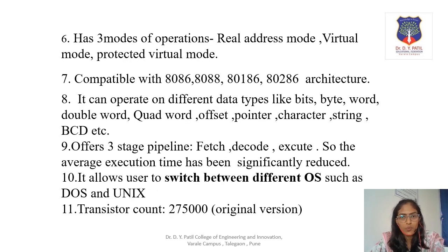It has 3 modes of operation: real address mode, virtual mode, protected virtual mode. It is compatible with 8086, 8088, 80186, 80286 architecture. It can operate on different data types like bits, byte, word, double word, quad word, offset, pointer, character, string, BCD, etc. It offers a 3-stage pipeline to fetch, decode and execute. So the average execution time has been significantly reduced.